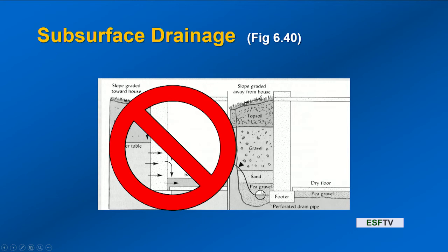So this flows from high potential to low potential, and essentially we have this amazing way to collect water. And now, instead of building up and going to your basement, water is brought to this drainage ditch and tile, and now it's graded away and moved away. And so we have water moving through gravel. So you place your sand and a little bit of gravel, so you have a lot of large macropores. Water is attracted here. And this is how to prevent the system from having a wet basement. This is called a French drain.